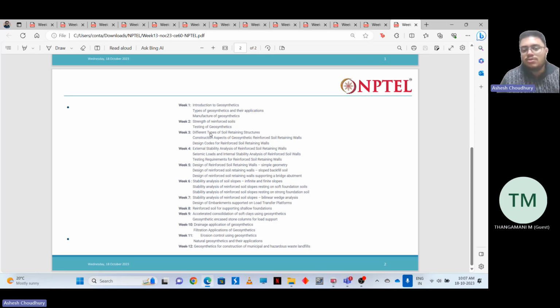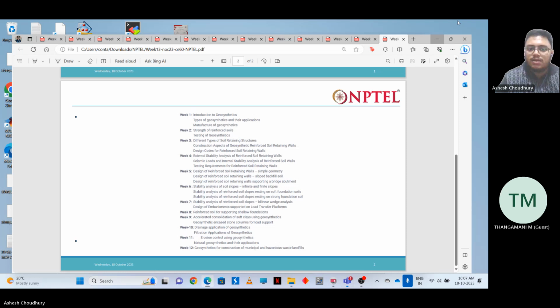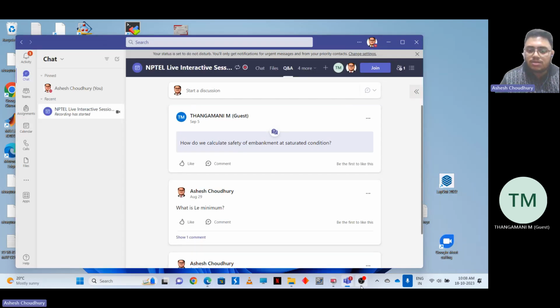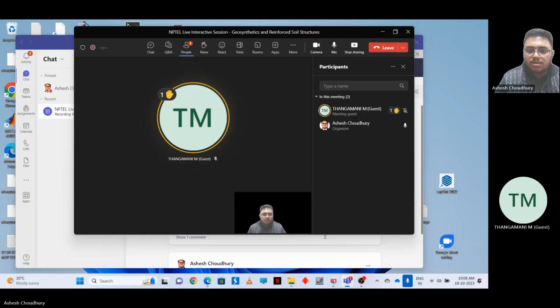And at the end, we saw liners, how we can design and calculate for geomembrane. We saw the different types of liners, properties of geomembrane, how to determine the thickness of geomembrane, how to calculate the runout length, and how to determine the depth of anchor trench, all these things. So with this, we will end today's session.